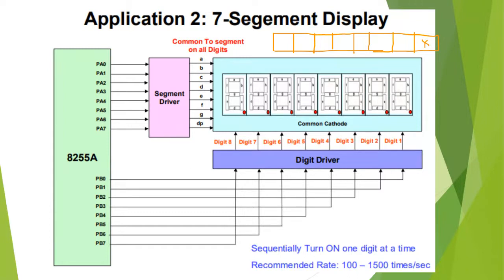Then this bit is for port B, and it is an output port, because we will send 1 or 0 to port B. This one is for mode 0. Next is port C upper, don't care. Then port A, also an output port. And the next two bits are for mode 00, and it is default 1. So it becomes 80, if don't care 80 or 89.